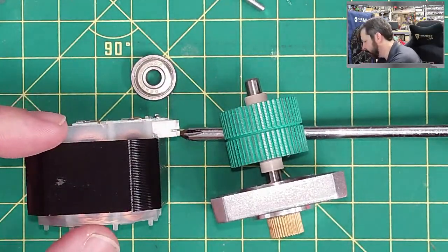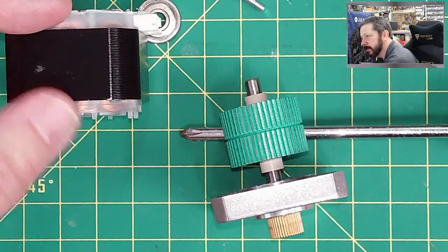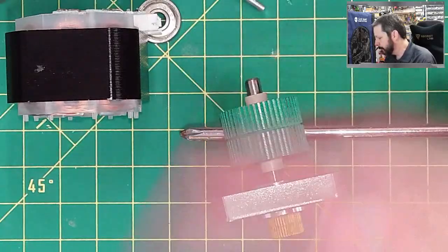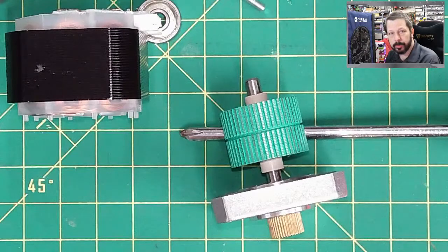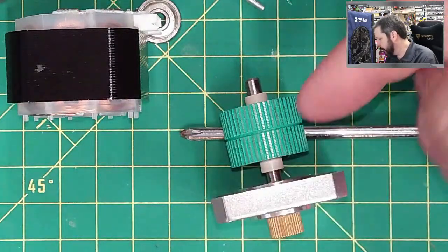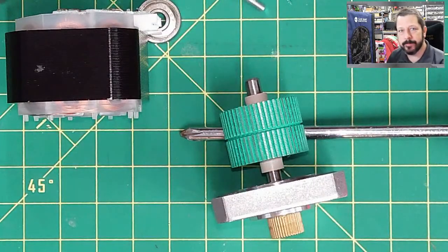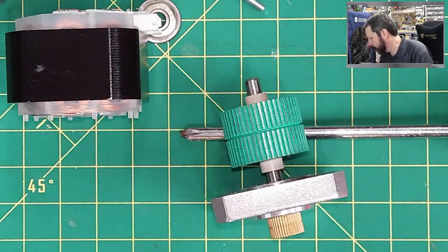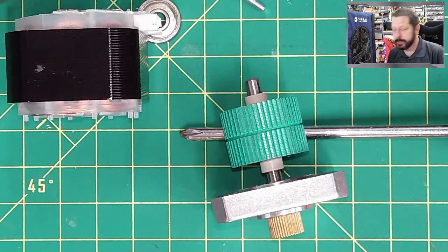You might have seen some of these stepper motors that are thicker in this direction than others. That's because they have more of these permanent magnets. So one of these, I don't know which one, is a north pole oriented magnet and the other is a south pole oriented magnet. And then if you had another pair, you'd have another north and another south. I've never seen more than 4 together. I assume you could have more than 4, but I've never seen more. So the more of these you have, the more torque it's going to be able to generate.